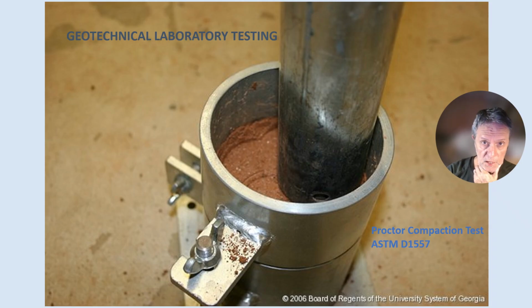So this shows a laboratory test in progress called a compaction test or a Proctor test, wherein layers of soil are placed in this mold. This cylinder is actually a hammer that's a piston hammer, so you bring the piston up in a hollow tube and then you let the piston drop and pound the material in this mold, which is a 4-inch diameter standard Proctor mold.